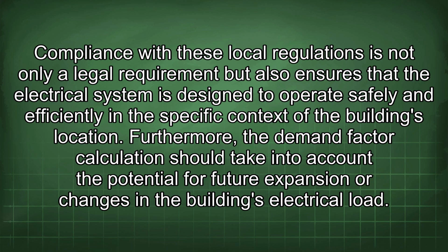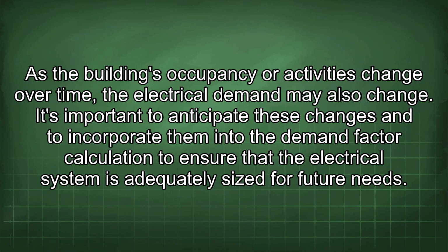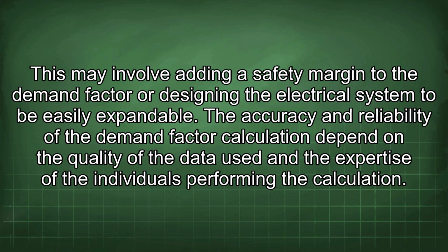Furthermore, the demand factor calculation should take into account the potential for future expansion or changes in the building's electrical load. As the building's occupancy or activities change over time, the electrical demand may also change. It's important to anticipate these changes and to incorporate them into the demand factor calculation to ensure that the electrical system is adequately sized for future needs. This may involve adding a safety margin to the demand factor or designing the electrical system to be easily expandable.